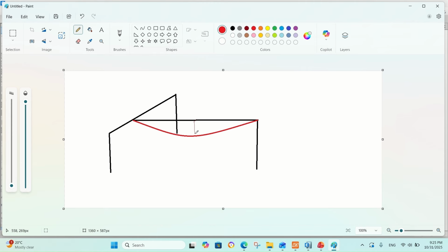So this deflection, we read here, when I have both ends of the beams fixed in translation. So here the deflection value is 0 and here the deflection value is 0. So this deflection relative to the beam ends is, for example, 15 mm.